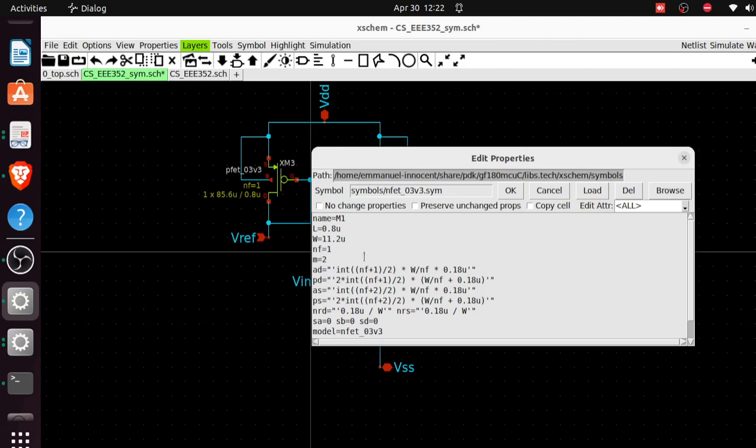Anyhow you want to do it, maybe you have a fixed number of devices in mind already, maybe you don't want to go beyond 4 devices, so you can do 22.4 divided by 4, and whatever you get, that's 5.6. That will be the new width of the new parallel devices. But for me, I think I just want to go with 2 devices. Since I want 2 devices, I'll divide the original width 22.4 by 2 and I'll get 11.2.